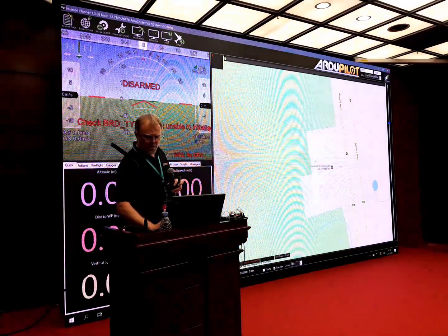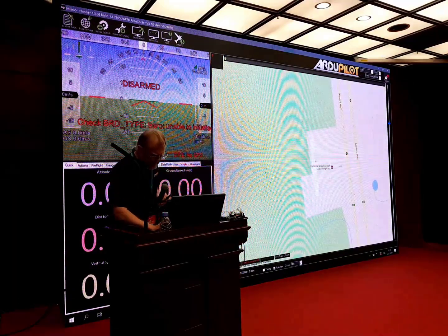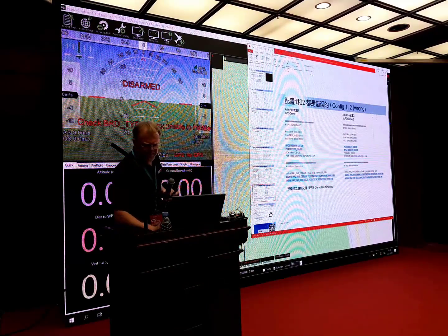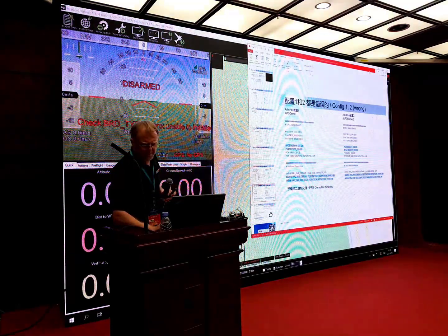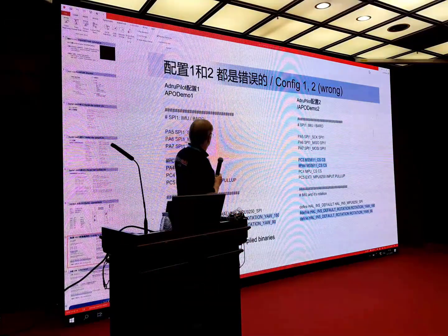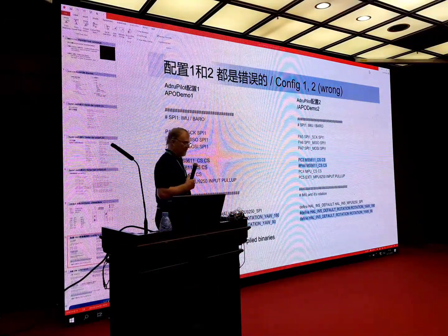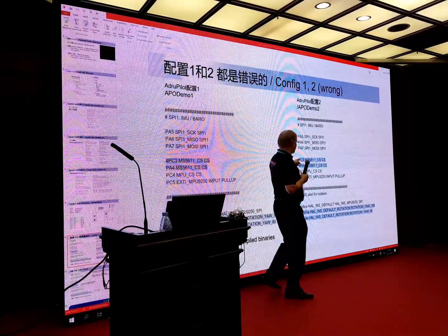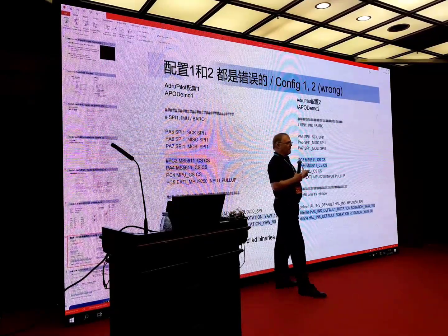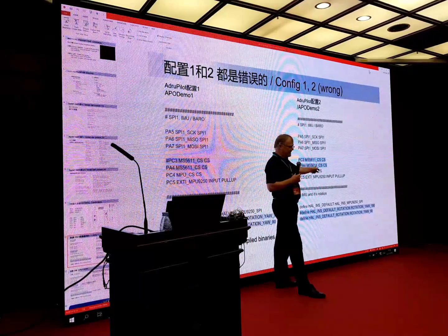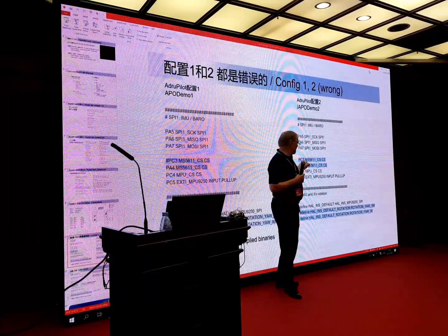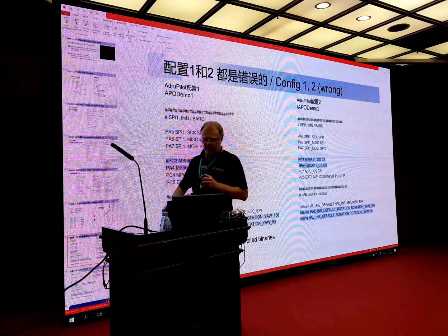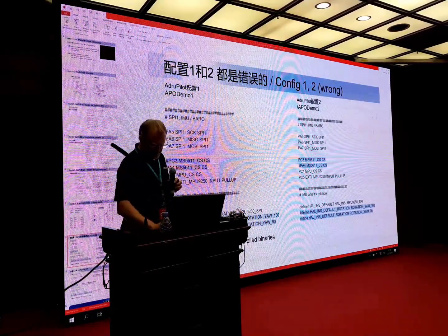All right, let's disconnect. And now I'm just making this one bigger. So now we had this inside the board, and we noticed, oops, we had a mistake in here. We had PA4 made for the chip select for that. So let's put in the firmware that has PC3 for the chip select, which is correct.